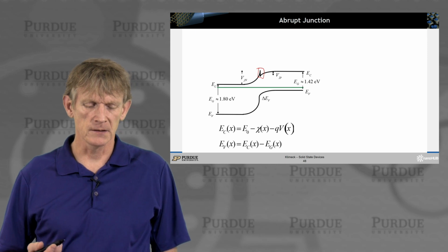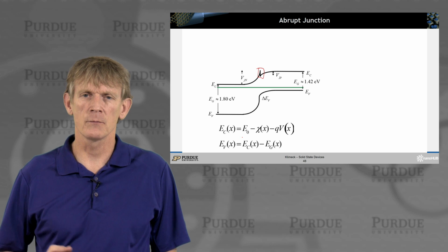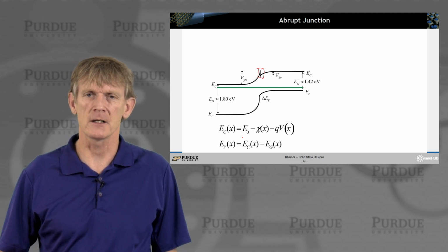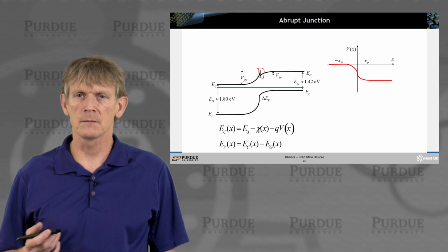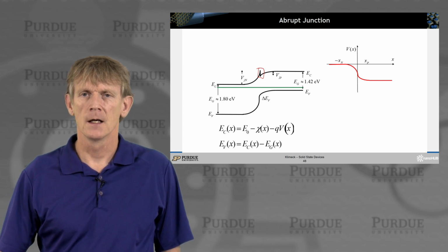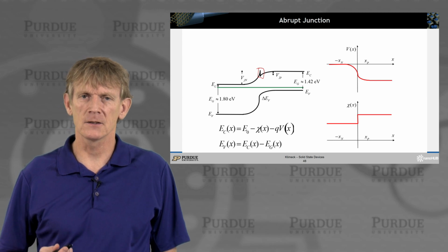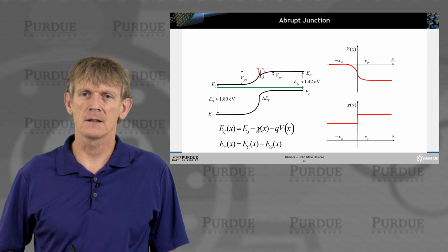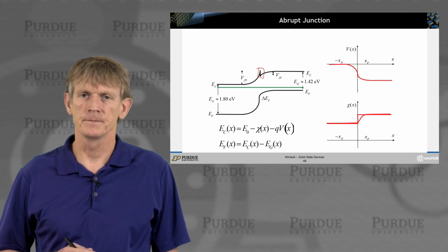And we can write down the valence band as a difference between the conduction band and the gap. Okay? So we can obtain these values spatially. We've built in this built-in potential, and we learn how to calculate it. And together with the built-in potential and the difference in the electron affinity, we can now obtain the overall structure.